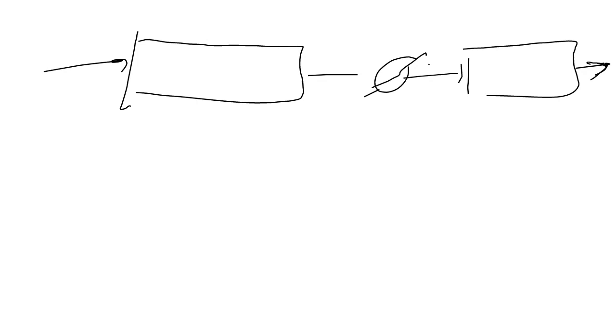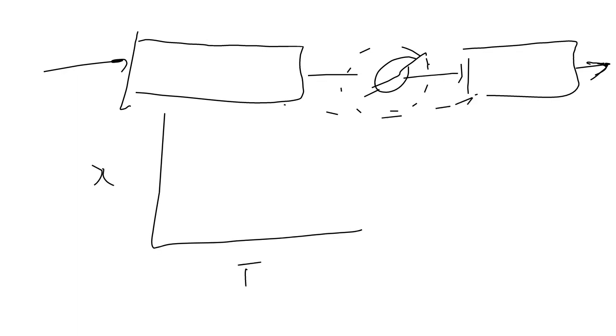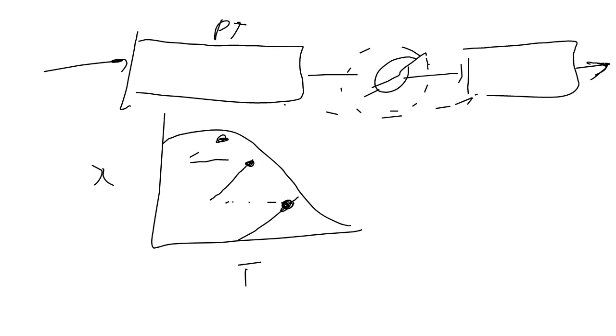But the advantage of having this intercooling that we have with the CSTR reactors, and that's why you will not do this for a PFR reactor, is the fact that I can adiabatically determine where the maximum in the rate is, operate there, cool, go to a maximum in the rate, cool, and operate that reactor at that maximum in the rate. And now what we must realize for the PFR is that that doesn't exist. I do not operate at a maximum rate. I operate at lots of rates inside my PBR or my PFR as I follow.